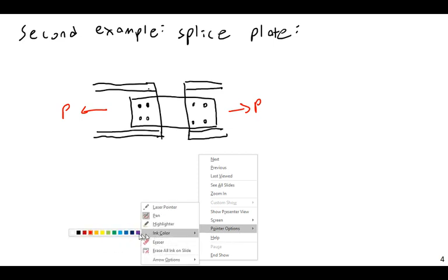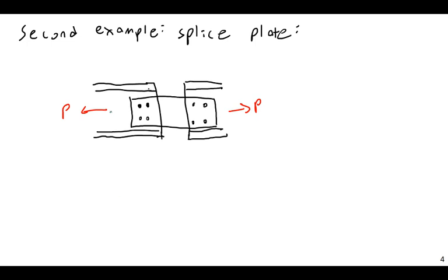And I would also ideally, if I wanted to avoid any eccentricities, want to make sure that the centroid of my bolt group, the centroid of the load, and the centroid of the wide flanges all lined up exactly or as close as possible. So these bolts will have a centroid. You can have a centroid for anything, even holes.